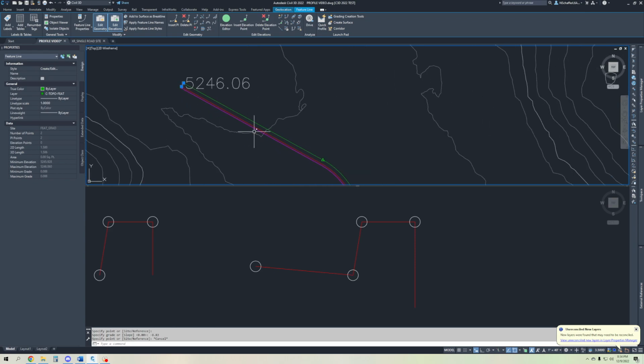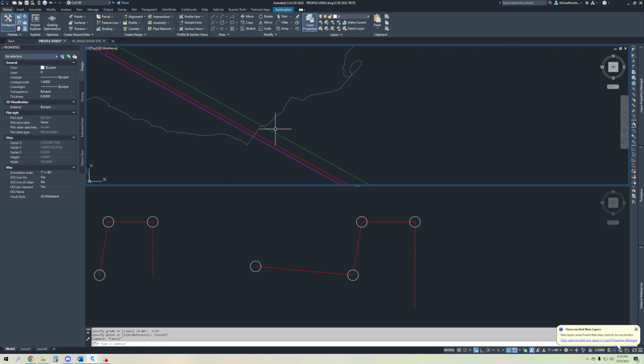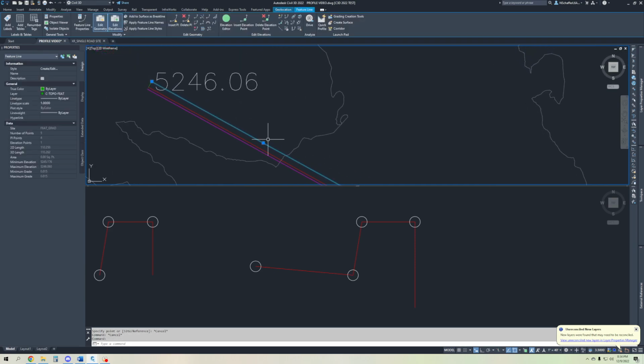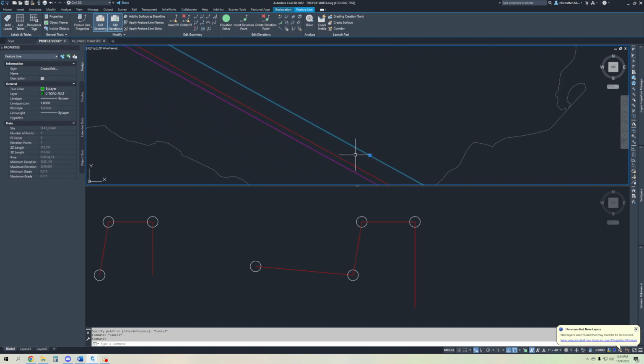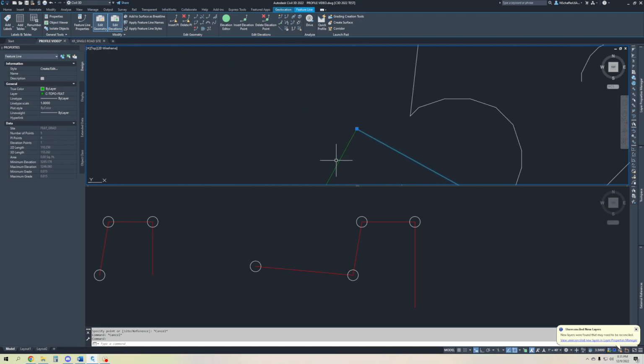One tip that I've been given is when you have your PI points, to typically draw lines like this all the way through. So you would have one here, and basically imagine that we have lines drawn as I'm talking about at your PIs, and you would draw a line going from this point to this point, this point to this point, this point to this point. That way you can use Quick Elevation Editor to constantly check yourself.